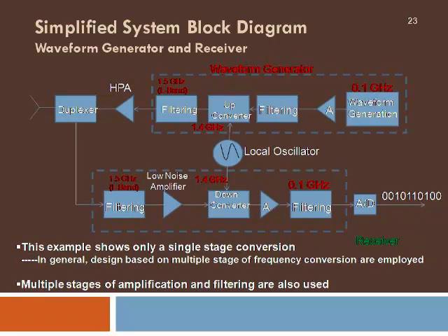The received signal is directed to the receiver by the duplexer, and the first stage is going to be a filter to remove the unwanted noise. Then normally we are going to use an amplifier which will be a low noise amplifier, because the signal is highly corrupted with noise. We don't want the amplifier to add any more noise into it.